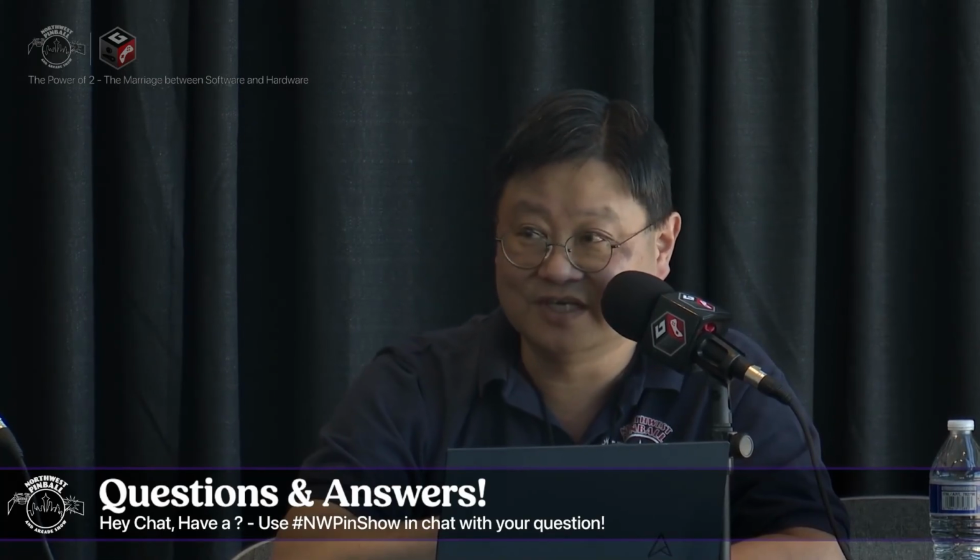It's processor specific. So in the Intel world, everything is little endian. That is how Intel operates. They are always little endian. For the 8-bit microcontrollers, the 6502 is a little endian processor. It's not Intel, right? The Motorola world, the 6800, 6802, Motorola is always big endian. So if you've got code that's written for Motorola, you'll always have data that's in big endian format. And it doesn't matter because you won't be able to execute that code on a little endian machine because it's a completely different instruction set architecture. Right. They're not compatible. Okay.